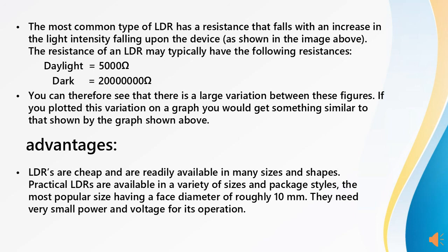Coming to advantages, LDRs are cheap and are readily available in many sizes and shapes. Practical LDRs are available in a variety of sizes and package styles, the most popular size having a face diameter of roughly 10 mm. They need very small power and voltage for their operation.